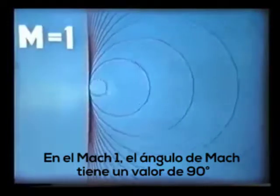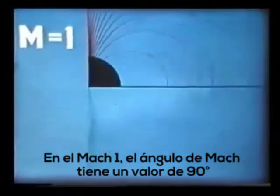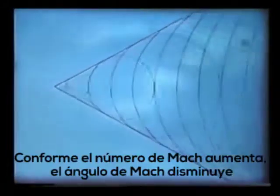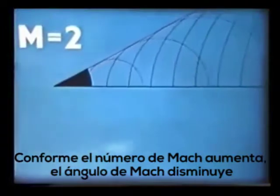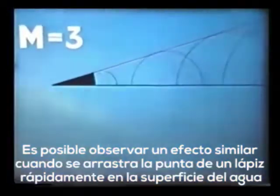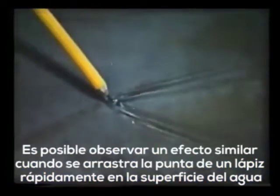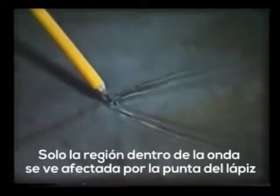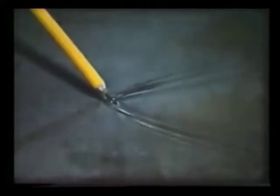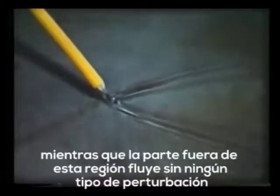At Mach 1, the Mach angle is 90 degrees. As the Mach number is increased, so the Mach angle grows smaller. A similar effect can be seen by dipping the point of a pencil in a fast-moving stream of water. Only the region inside the wave is influenced by the pencil point.